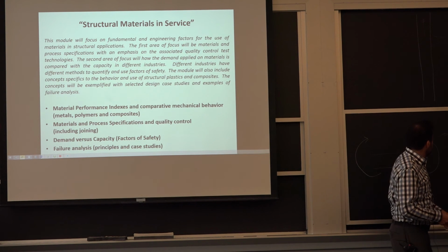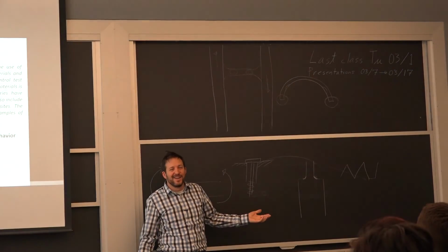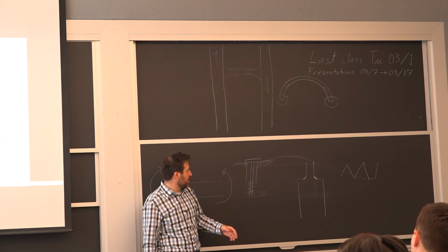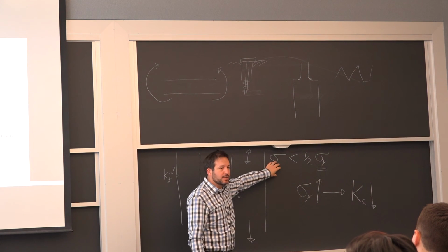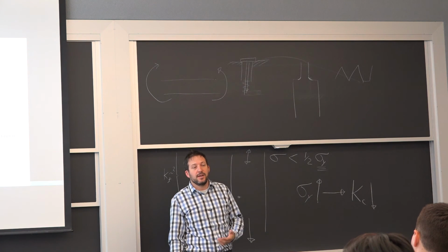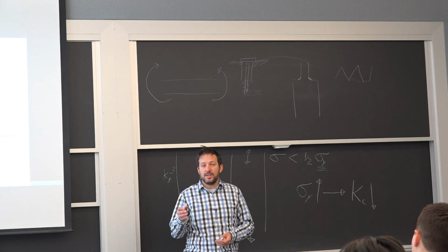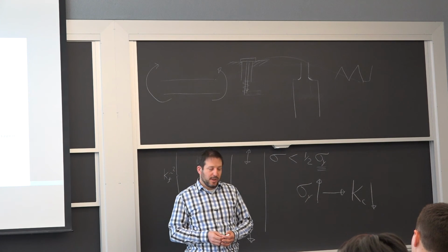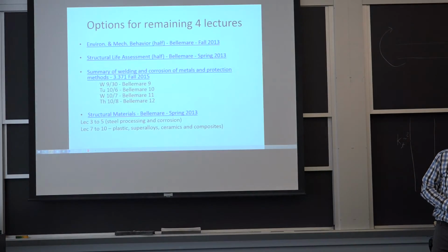So if somebody wants to start saying, well, maybe we need to redesign this valve. No, the valve's fine. You just lost a factor of 2 or 3 on your minimum load. This equation here will start causing fatigue because you had corrosion. So that's not an issue with the design at all, and you just move on. You say, this one piece of information is not a good reason to go back and make the valve stronger. If something else happens, then of course you need to keep your eyes open for that.